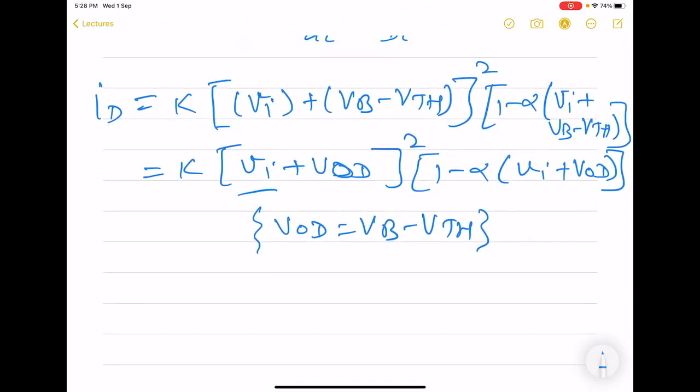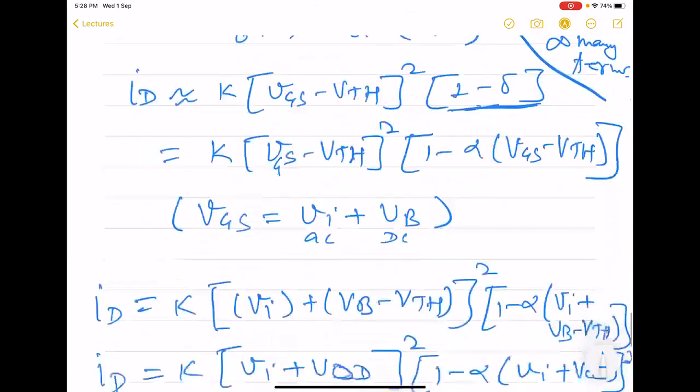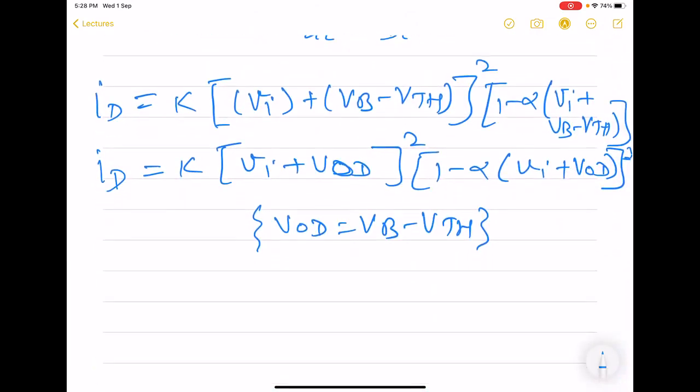So now you can see that we have VI here with second power ultimately, and VI here with first power, first order. So when you multiply, of course, VI now will have third order. The maximum power that will appear for VI is third power. But if we had taken a linear expression for expansion of this term, then we would have got the other order terms as well. But we are interested in P1 dB and IIP3, which depends upon the first and third order.